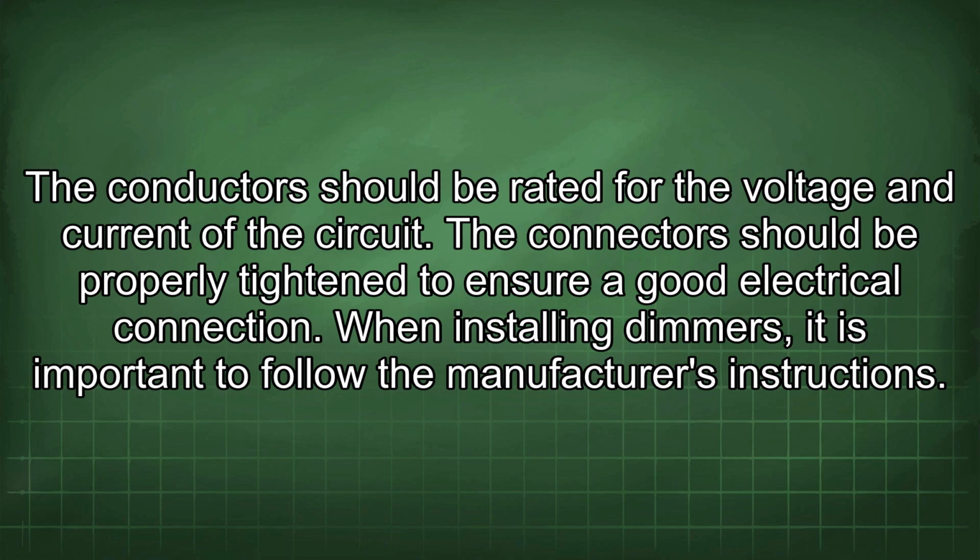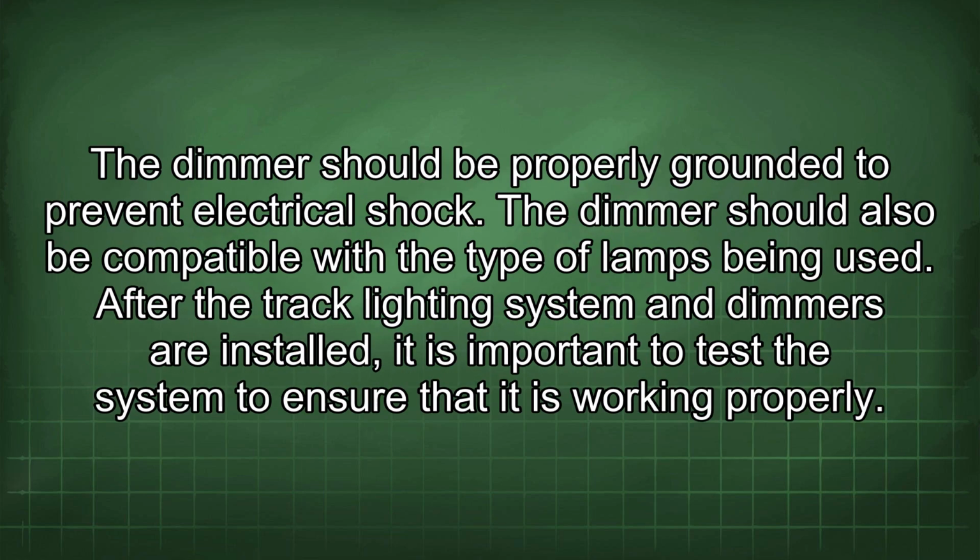When installing dimmers, it is important to follow the manufacturer's instructions. The dimmer should be properly grounded to prevent electrical shock. The dimmer should also be compatible with the type of lamps being used.